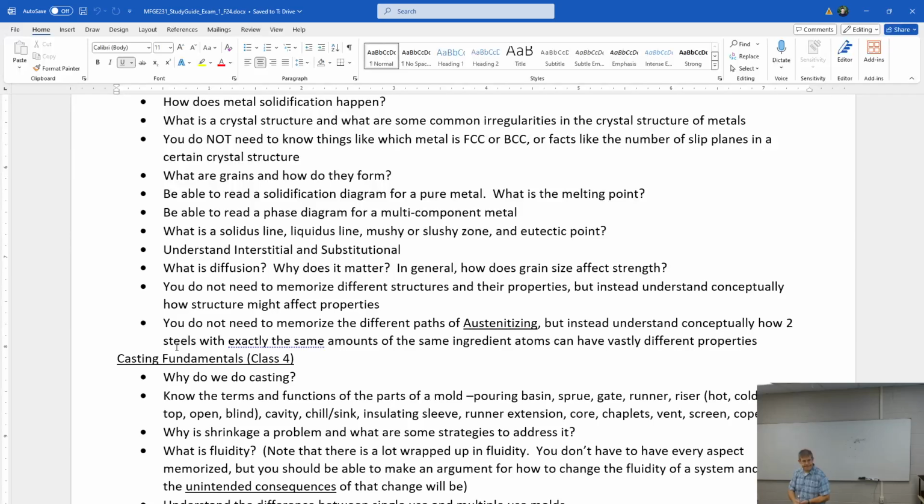Yes. So for impurities, to get past that, we would heat or do more hot work on the part. Well, it depends on which impurities. If it's interstitials, you can go to the recovery range and you can diffuse the interstitials. You lose a little bit of the strength, but you gain a lot of ductility. If it is substitutional, you probably have to go to the hot work region to reform the structure to get them to move. Some substitutionals will diffuse, but it takes a lot of energy to get it to happen. Gotcha.